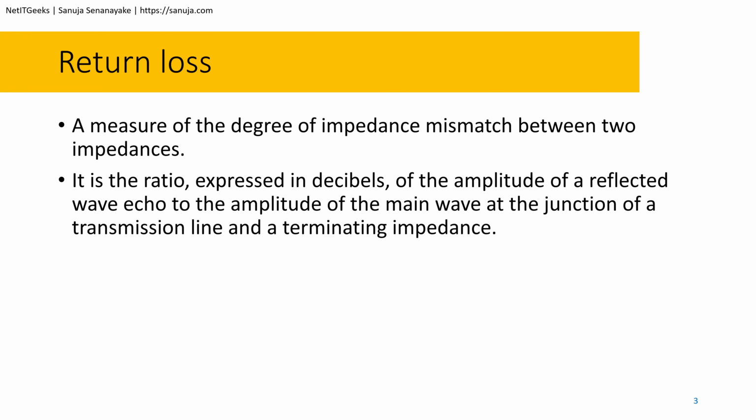So return loss decreases, in other words, worsens at higher frequencies as even small impedance mismatches become more significant, right? The longer cable can also amplify the effects of impedance mismatches. So you need to understand that for your exams when you are discussing return loss. So that's our first definition.